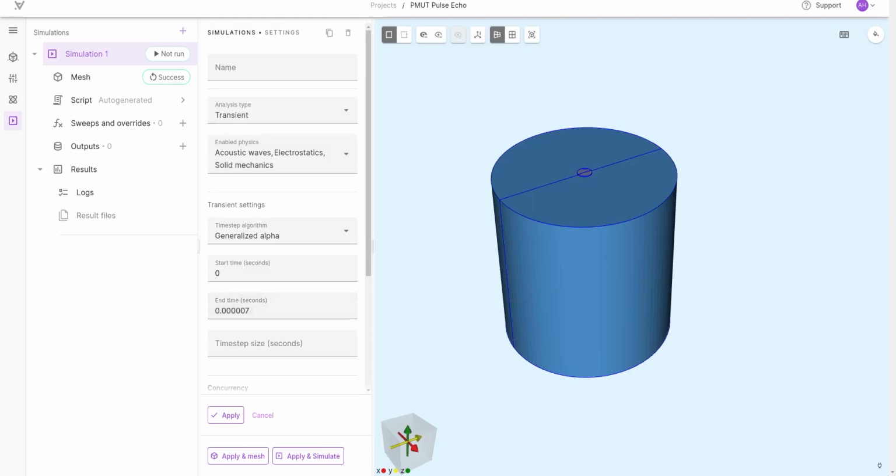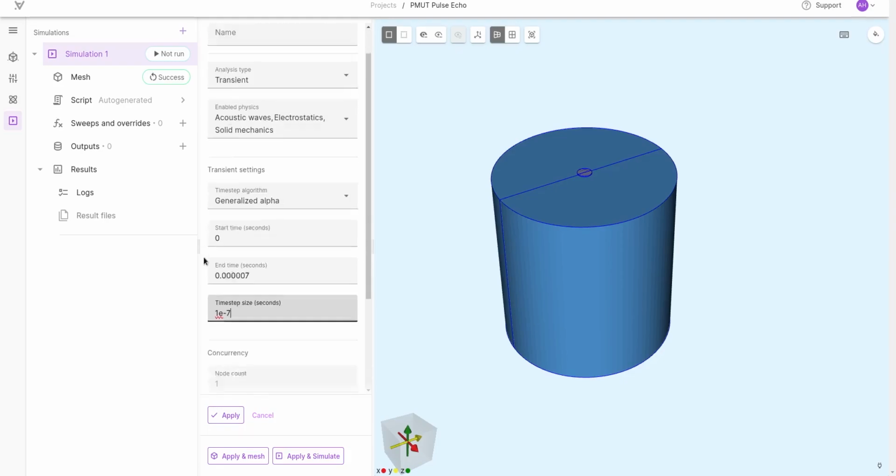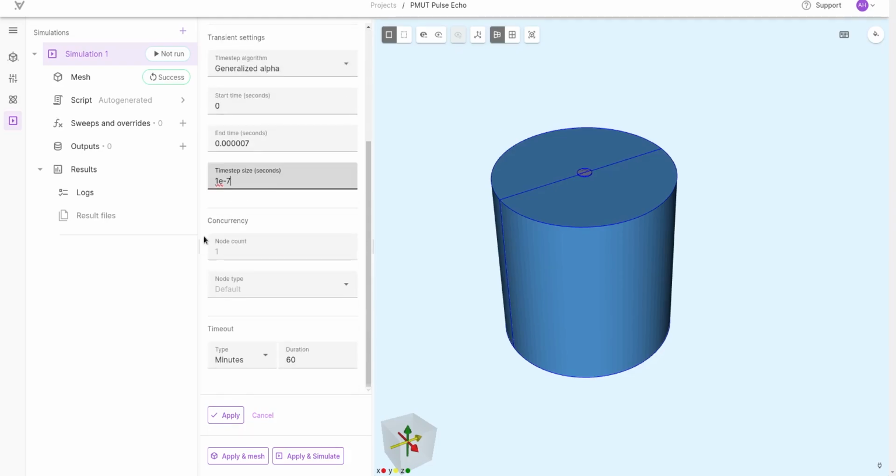And then the time step has to be small enough to capture the highest frequency that you want to capture. So it's a second order accurate scheme. So with 5 time steps per period, you start to be likely quite accurate. So this number corresponds to capturing correctly the highest frequency we want, knowing that we throw in a big harmonic content when we don't put a perfect sine and we don't analyze in steady state. If you put a pulse or something like this, you definitely have more harmonics excited as well. But we already covered this part.